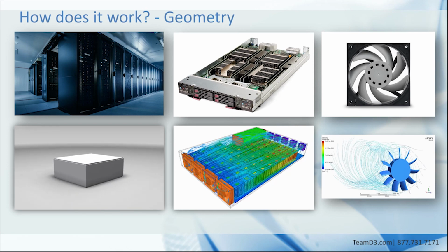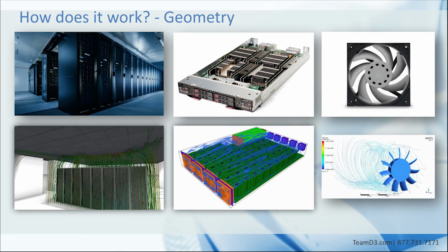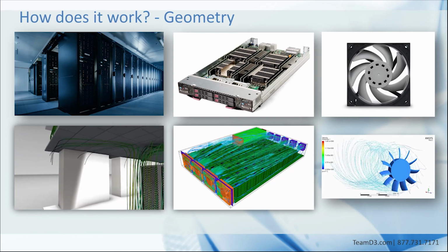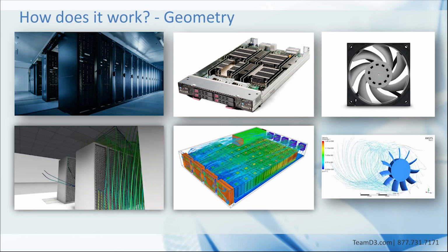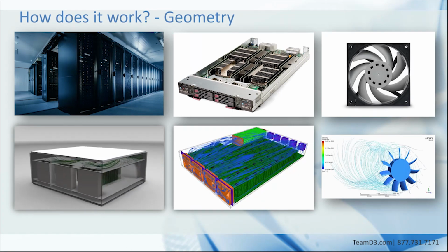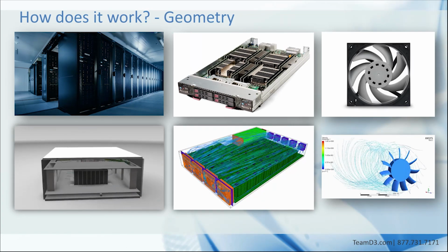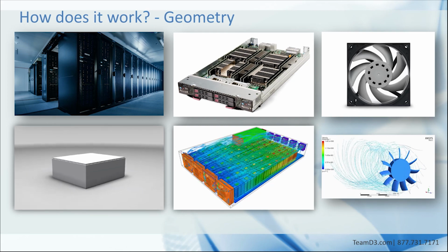So the geometry decisions depend on what we are designing. The level of detail is always a trade-off between realism and the cost of the analysis. The effects of the smaller details may be less consequential than you think. Highly simplified geometry is often employed to compare one design candidate to another, especially earlier in the design process when that detail is not developed yet.